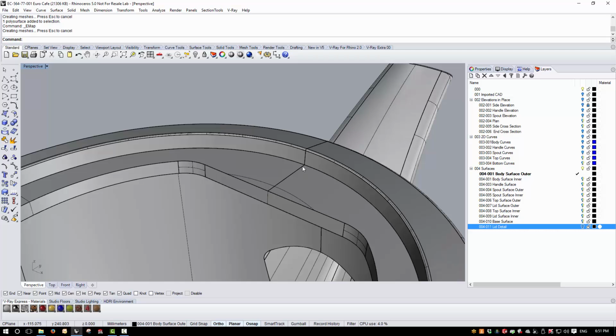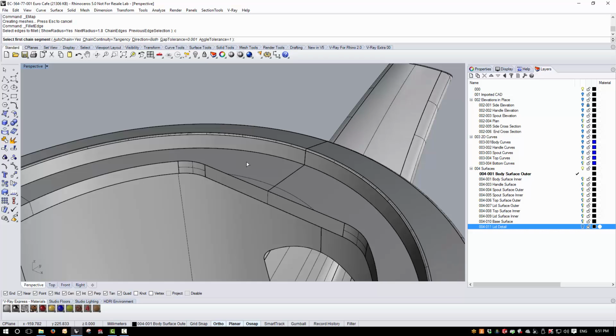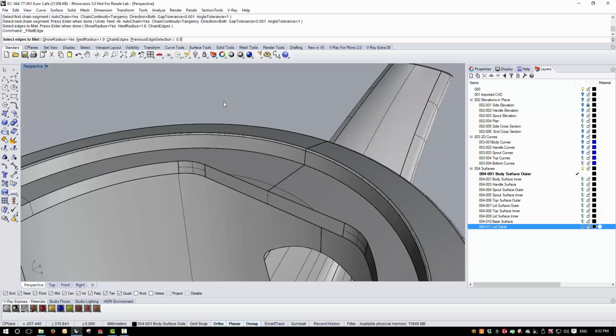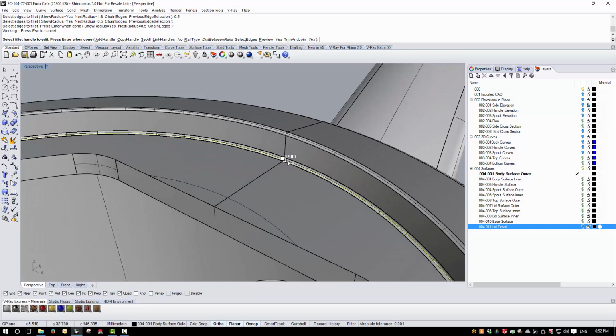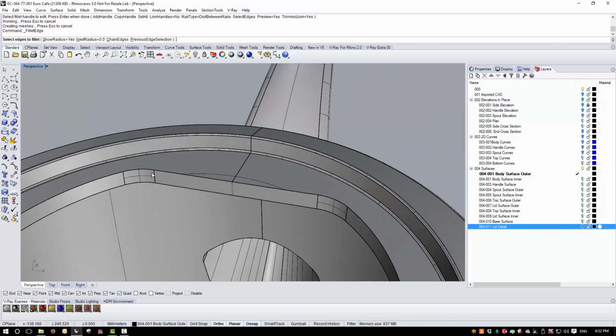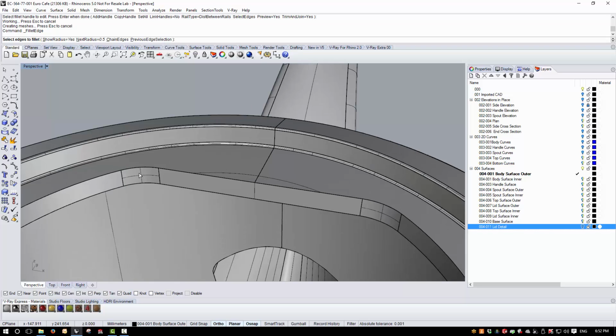and just fillet off these edges. So I'll put a 0.5 on this edge. So this is the edge here where on the lid I've got the large radius to make sure that we don't stick in that corner. And then I can put a larger radius here so we don't have the same problem on this face.